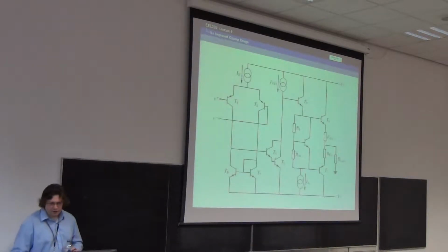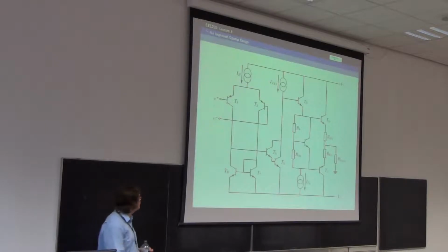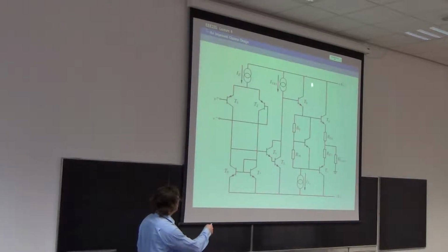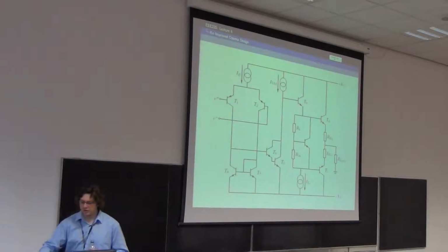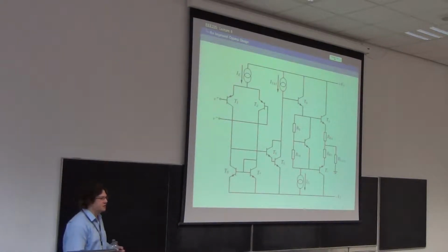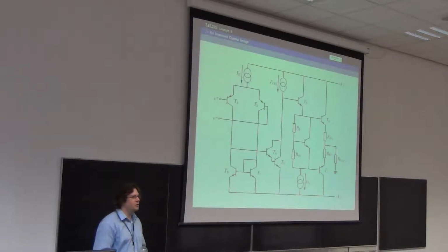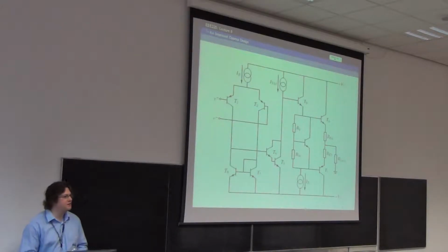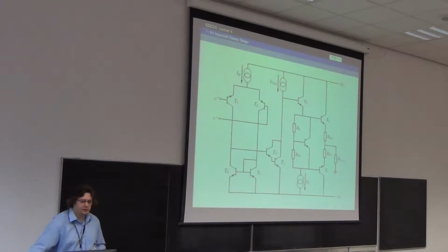It could be that this stage here, I could have made it push-pull, ditched that, and that stage would have been 180 degree conduction per transistor, and this stage could have been 180 degree conduction per transistor. I could have popped that into there as well, that would be fine, as long as I adjusted the voltages. This particular circuit has no special significance. It's not a gold standard, it's just one of thousands and thousands. So don't hang your hat off it or anything.